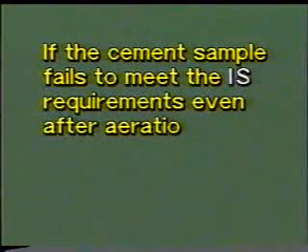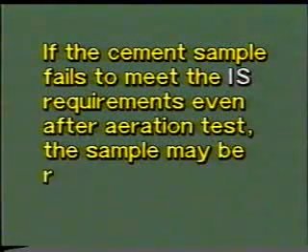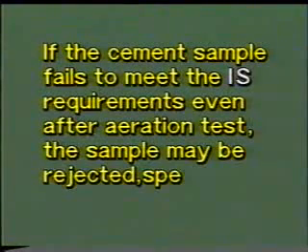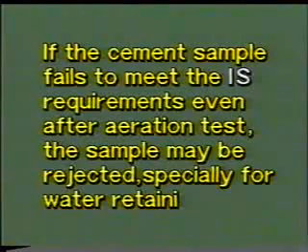If the cement sample fails to meet the BIS requirements even after aeration test, the sample may be rejected, especially for water-retaining structures.